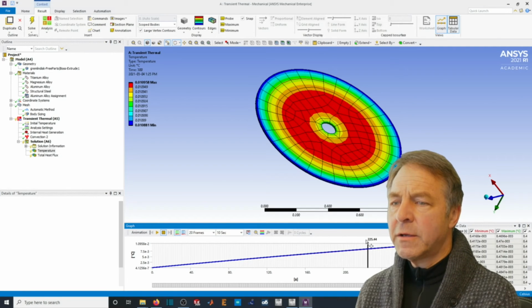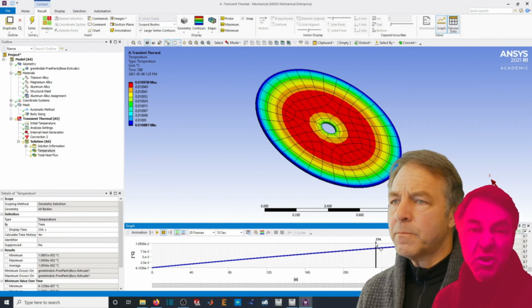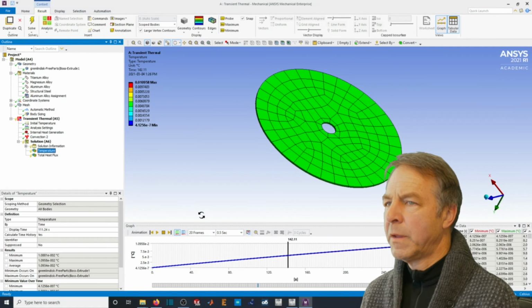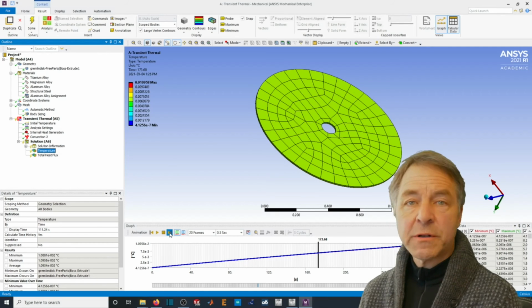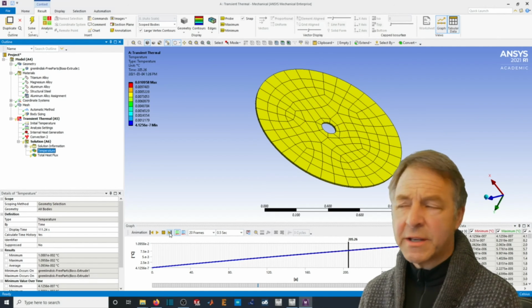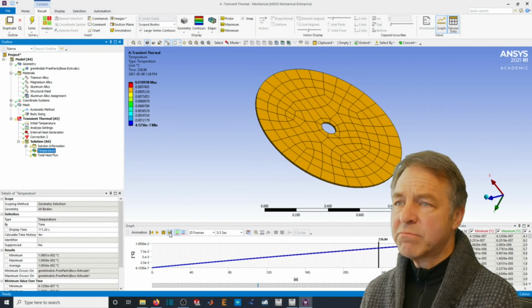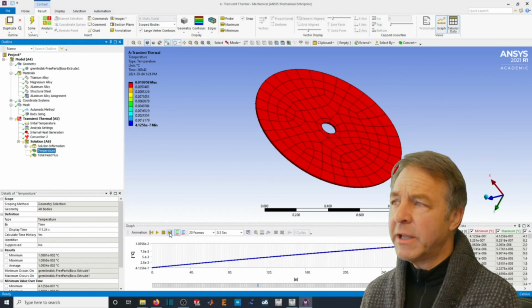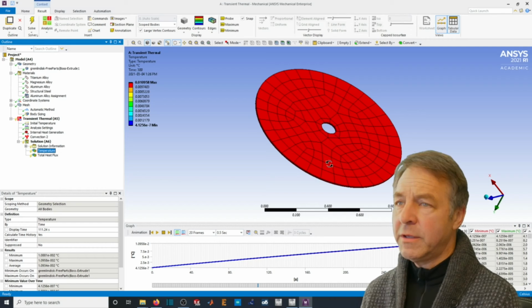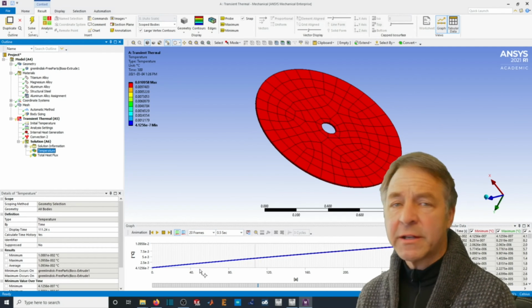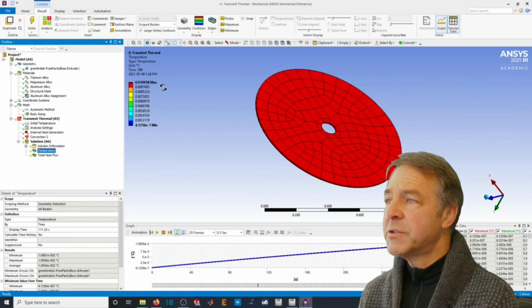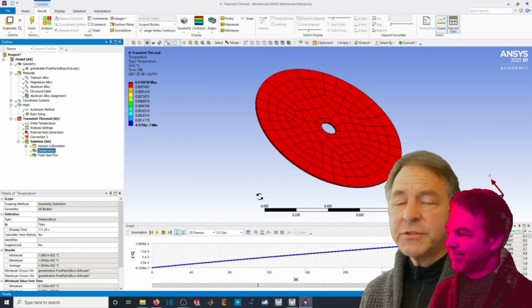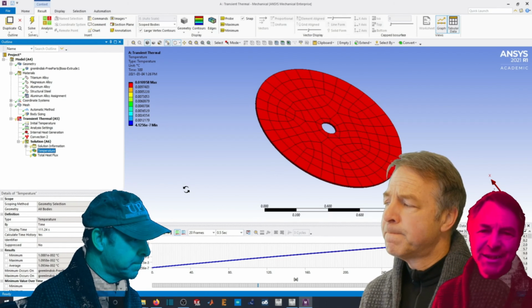If I just look at a particular time, maybe you just did it wrong. So if we look at any particular time, the results look rather surprising because at each time step, the temperature is effectively constant in this aluminum plate. And the hottest temperature is at the end of the 300 seconds, but it just keeps getting hotter. The other thing that's a bit surprising is that it's only 0.01 degrees C change in temperature.